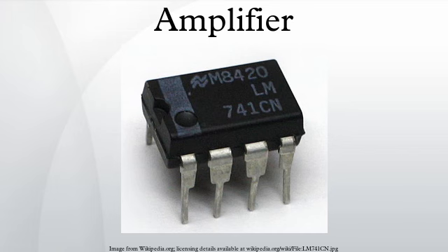The Sainton amplifier consists of a Class C primary or carrier stage in parallel with a Class C auxiliary or peak stage. The stages are split and combined through 90-degree phase-shifting networks as in the Doherty amplifier. The unmodulated radio frequency carrier is applied to the control grids of both tubes. Carrier modulation is applied to the screen grids of both tubes.